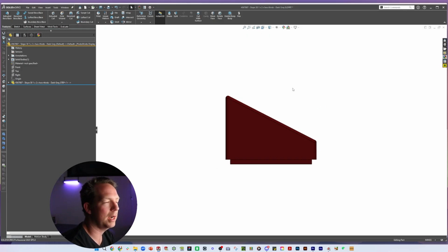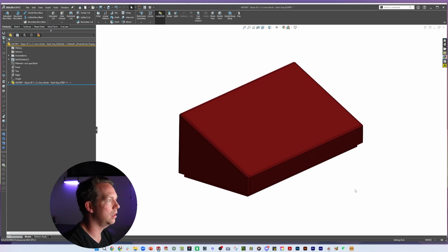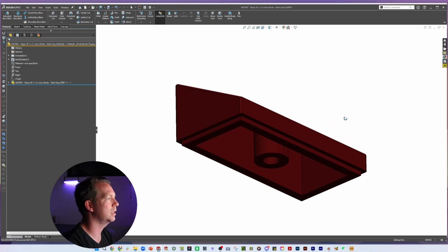Now, when we are recreating it, there's absolutely no problem using the existing geometry there, but what we need to be aware of is that later when we delete that original step file import, we want all our references to remain unlinked to it, okay? So you can add references to start to set the dimensions up, but then when you're done, you want to change those so that they've got their own relationships to, let's say, the origin or the other planes, but not to the original body. That is the key. Now, a couple of things I typically like to do with something like this.